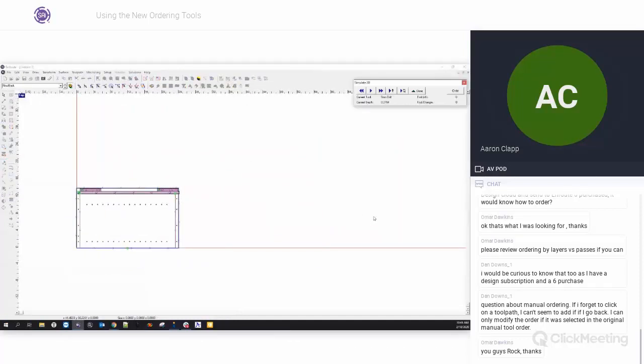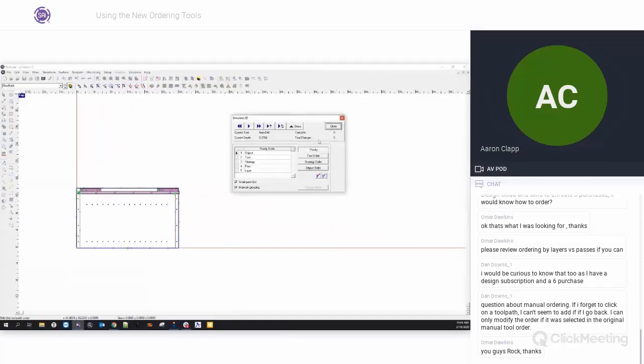And what this is going to do is if I hit output to simulate, I'm going to do layers, update order. And this will automatically start cutting in the order of my tools. So it should do it in the order. It looks a little bit weird, but it's doing the drill holes right now. It's because I have a drill bank set up here.